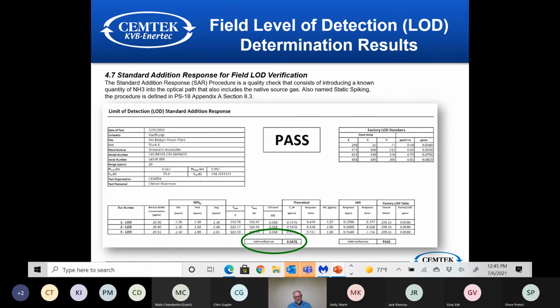They go up, they clean the optics, the moisture is still high. They notify operations that, hey, you have a tube leak. And they say, no, we don't. They say, you've got one that's developed, the moisture's gone up. Keep that in mind. If you shut down, you need to go check those tubes. And they've been accurate every time.